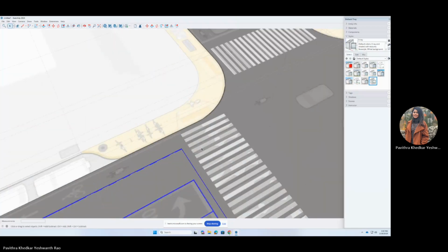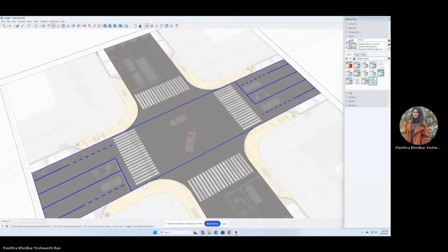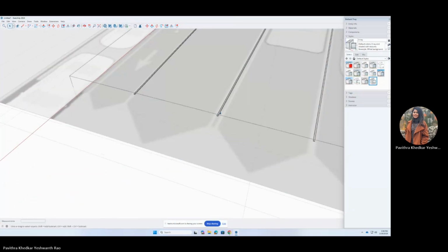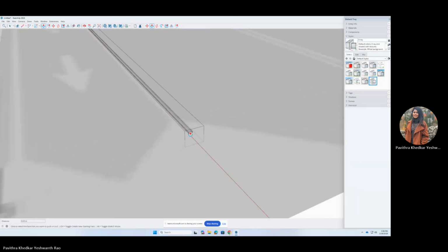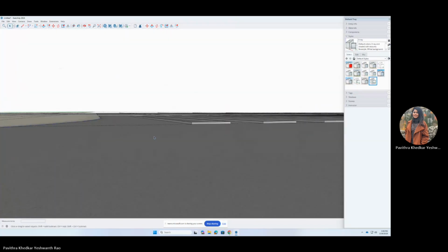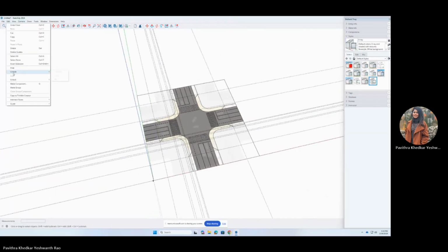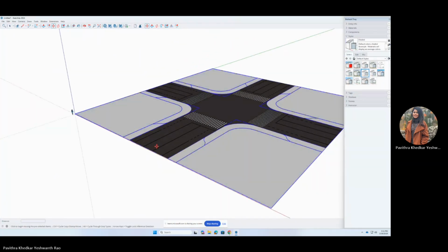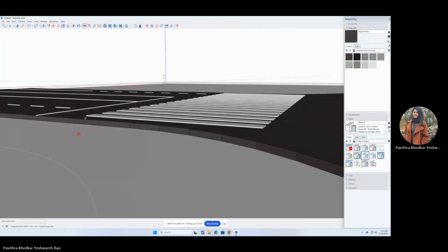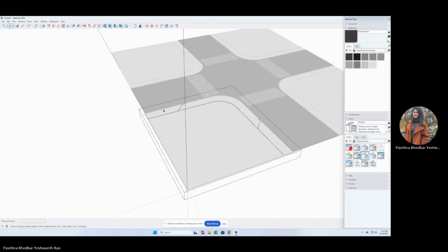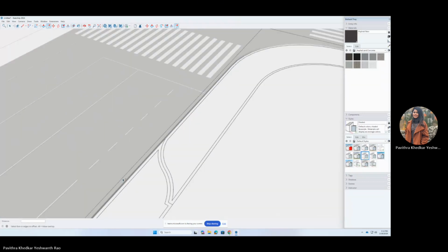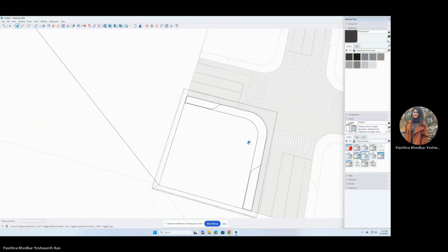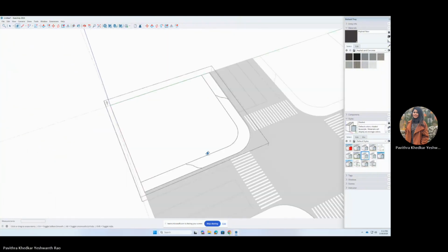Ensuring decals align with the road surface. Verify that decals are properly placed on the road surface and are not floating around. Floating decals can cause issues with rendering, especially when adding shadows and light. So be very careful when you're placing the decals. Whenever you place an object, make sure that you're holding onto one of the object's edges or corners. This will ensure that you place it correctly.